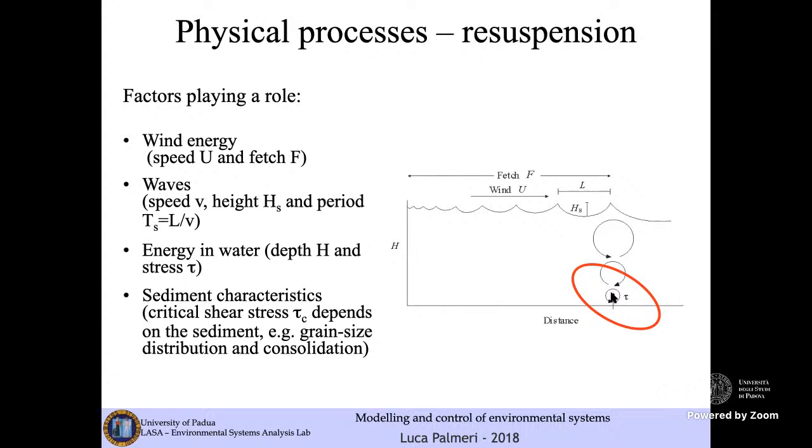So this vertical vector, shear stress, pushing material upwards from the sediment increases. So I recall that we have said that there is another force, the critical shear stress, depending on the characteristics of the sediment. The critical shear stress is a vertical force as well, this time oriented toward the bottom.